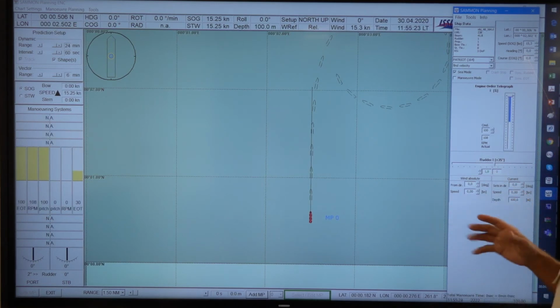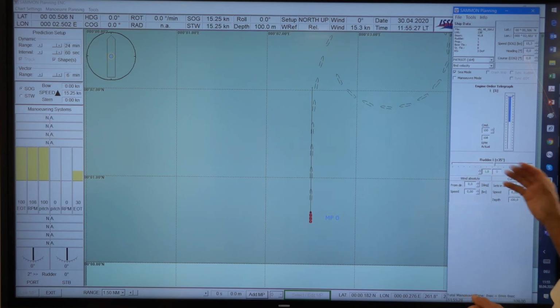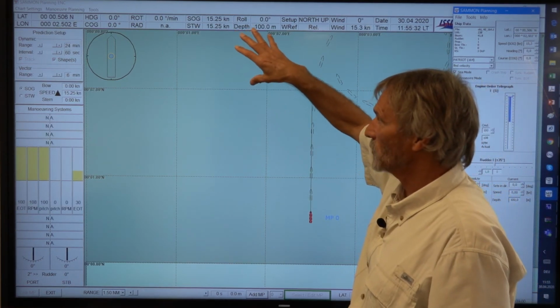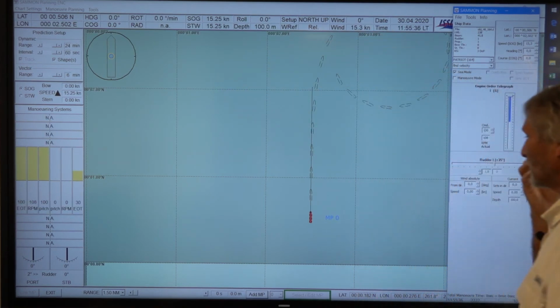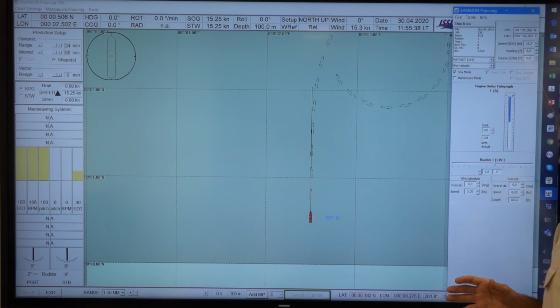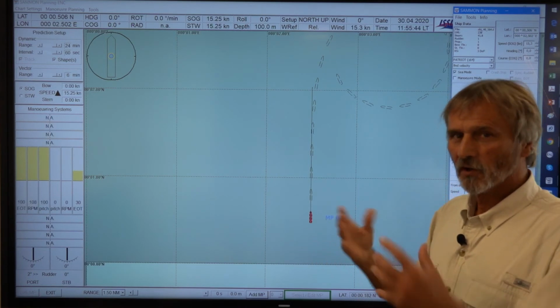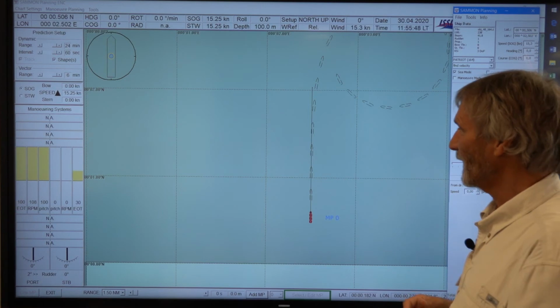A change from 1.7 to 1.8 degree of rudder changes from port turning now to starboard turning. So this indicates already a very high instability, and this ship starts turning from its own will, so to say.